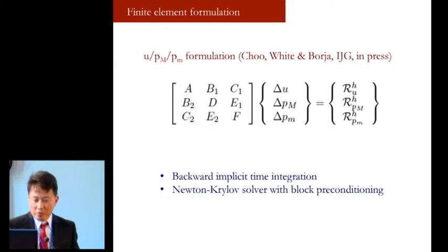So we employ the backward implicit time integration. The problem is now going to be considerably larger than it is for the single porosity case. So we also employ a Newton-Krylov solver with block preconditioning.